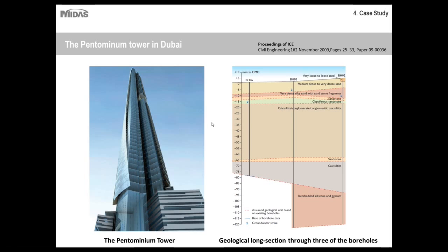Numerical analysis was used to evaluate the overall pile raft response under various static and wind loading combinations. Because of all the different loading combinations, numerical modeling was especially useful to take all of those into account. Also, there were some techniques used to optimize the foundation design, including the preliminary design testing. In order to optimize the design, a parametric study was performed in which several different variations of pile configurations were tested, not only for safety, but also for economy.